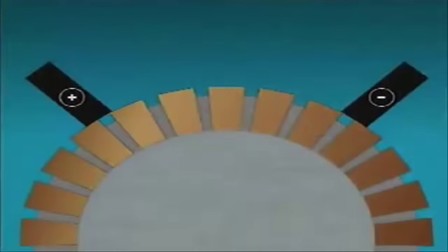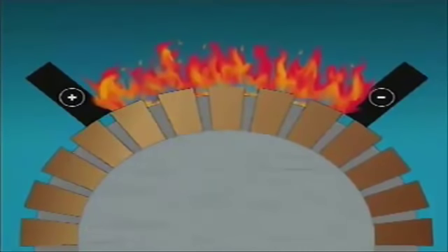When cracks or chips reduce the surface area of the brush, current has to flow through a smaller area. This may cause sparking or arcing between the brush and the commutator, and the brushes may heat up. The sparking may be minor, or it may be extreme, causing what looks like a ring of fire around the commutator. Sparking always indicates a problem in motor operation.